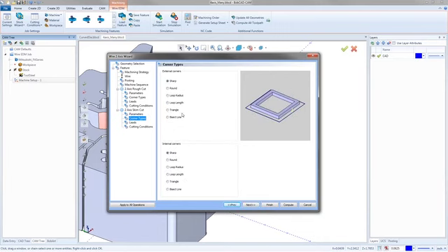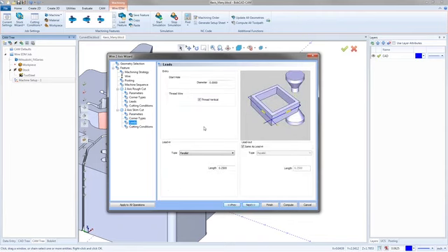Right here's our corner types. I'm not going to change much on there. Next, right here's the leads. So you can see this leads page matches the earlier leads page, even though normally the default would pop up with circular or perpendicular. Now we have the parallel settings because we used the Apply to All Operations button. So right there we have our length.